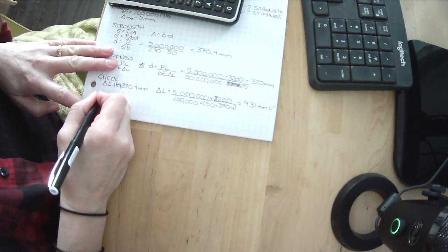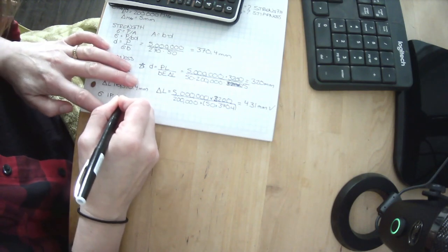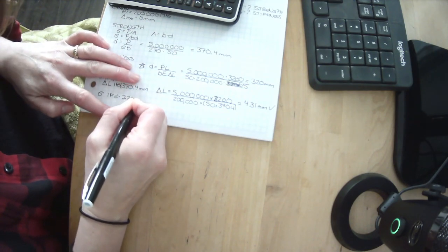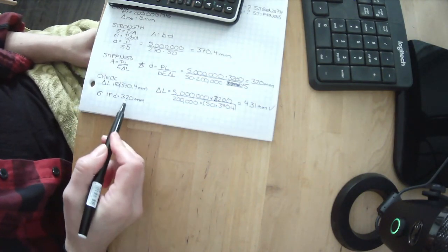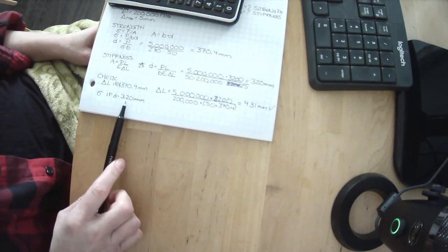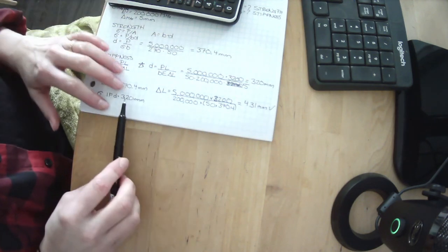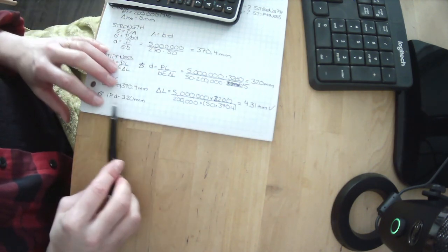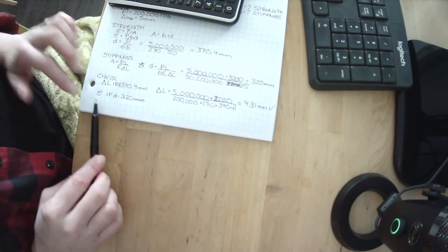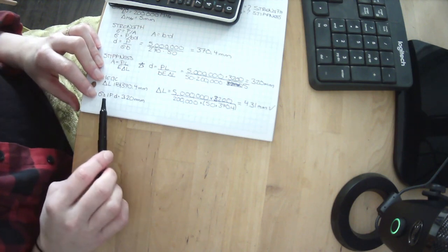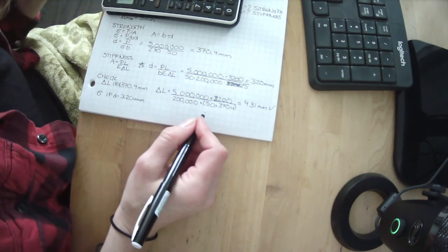Let's check stress if D equaled 320 millimeters. So what happens to the stress if we use the smaller dimension? Now you know, we talked about this when we talked about the shoes. Here's a quick gut check. If we decrease the area, does our stress go up or down? It's going to go up. So intuitively we know this should be higher than 270, which means our 320 isn't going to work for us. But let's just check that out.